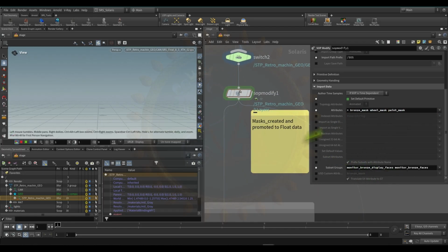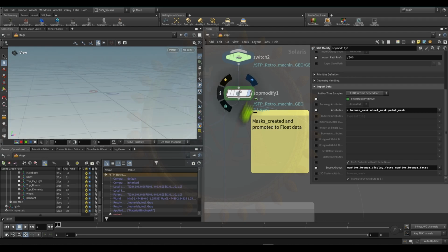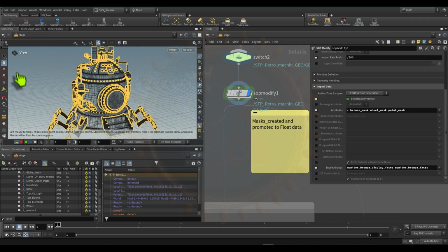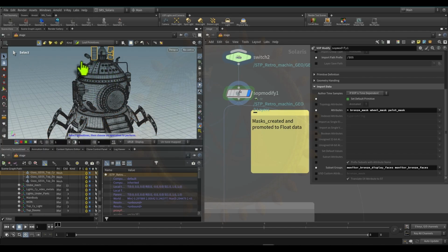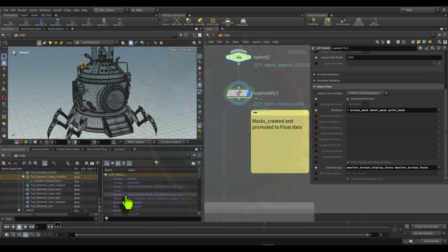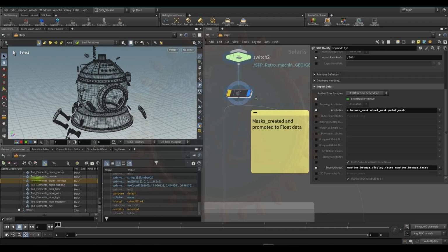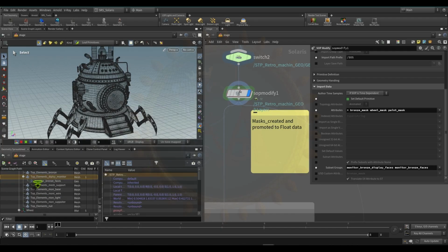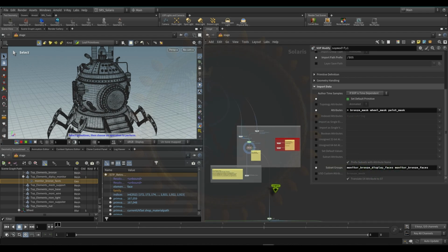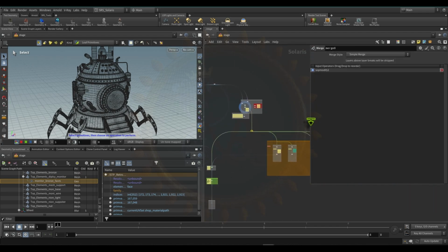Then how will it come to know that you have a mask? You need to use this subset group. Then only you can see the mask inside. So geo. If you don't have this, for example, I will disable this, it won't be there. It's a single mesh now. You're telling it's a separate mesh by this group. That's it. Next, I added one more merge for the subdivision purpose.